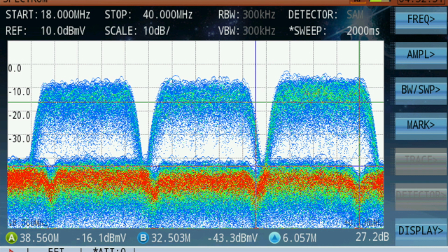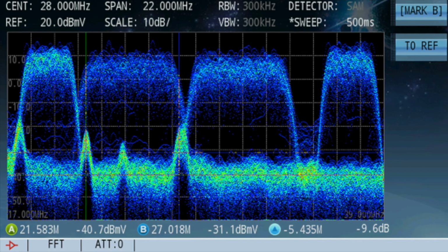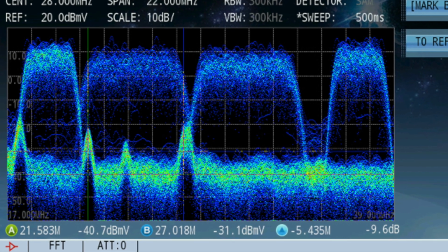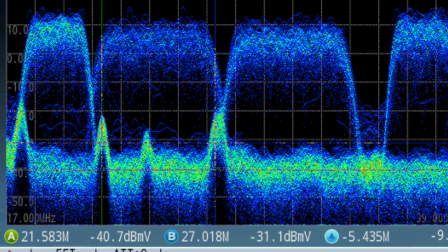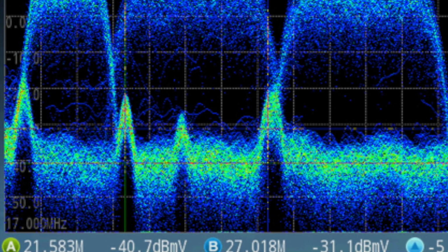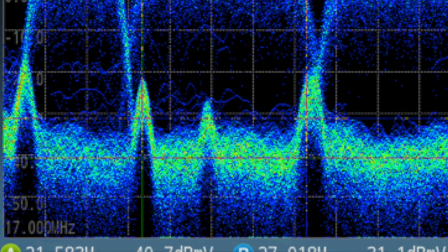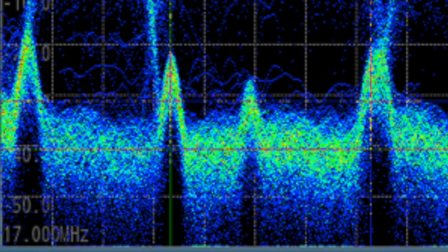The digital persistence spectrum function is based on fast Fourier transform technology, more commonly called FFT, with fast processing, and enables in-service detection of nasty transient noise and impairments, linear or nonlinear, hiding underneath upstream bursty signaling, like with bonded DOCSIS 3 upstream channels or with DOCSIS 3.1 OFDMA signals.